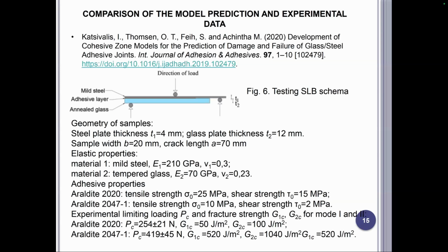The other is a plastic one. We found that our theoretical results are well aligned with test results from the experiment for one adhesive, Araldite 2020, but diverge for the other, as it was a plastic one. So this methodology cannot be applied to plastic adhesives.